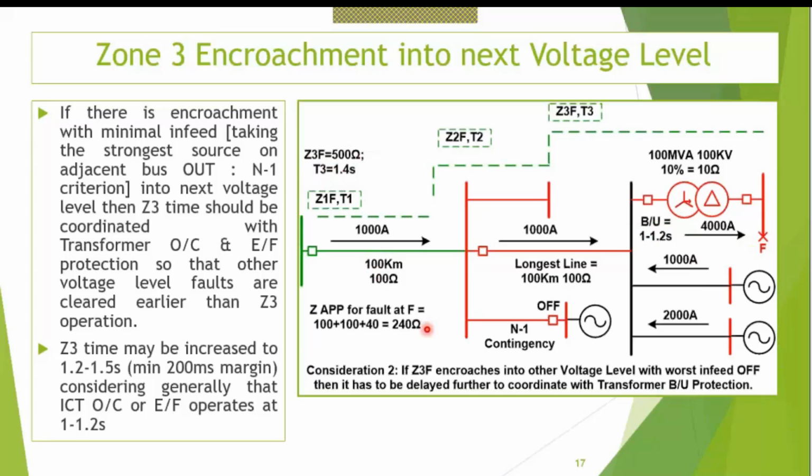The thing to remember during studying encroachment is that in the remote bus, do not switch off the strongest source. See, I did not switch off the sources over here. I kept these sources. I switched off these sources. If you switch on this source, then what will happen? This current will increase so that this fault will not be seen in zone 3.